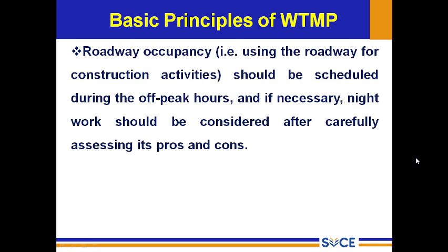Roadway occupancy, that is, using the roadway for construction activity, should be scheduled during the off-peak hours, and if necessary, night work should be considered after carefully assessing its pros and cons. Say if you are doing construction work by the roadside, or you are going to occupy the roadway, most probably try to do it during off-peak hours. If the work is going on for a number of days, then in such cases, the movement of heavy machineries, construction machineries, and material transportation should be carefully scheduled without affecting the peak hour traffic.